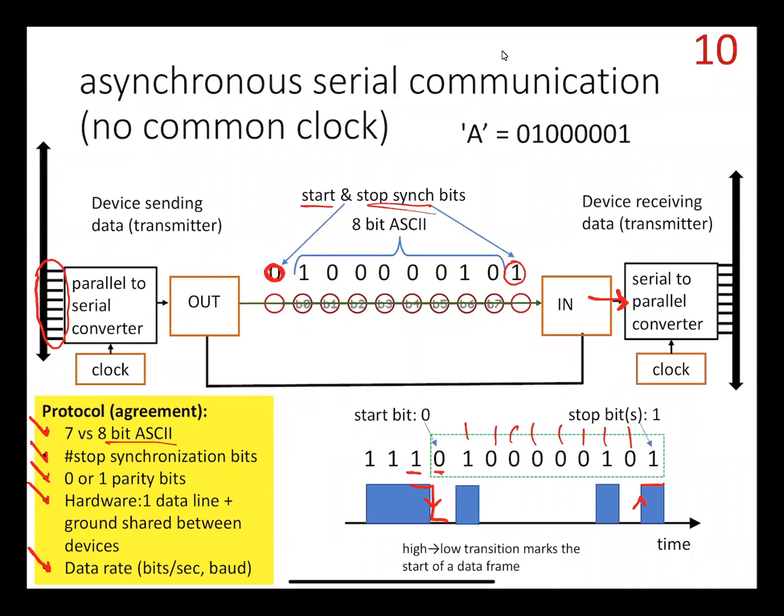We're getting toward the basics of how we do serial communication. You've probably heard of serial ports. You may have heard about RS-232. This is quite similar to what happens in RS-232, the difference being the voltages. In our device, we're using TTL, that is, a 0 is sent as 0 volts and a 1 is sent as 5 volts. In RS-232, those voltages are just sent as something other than 0 and 5.